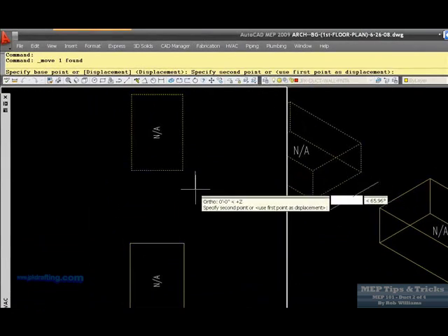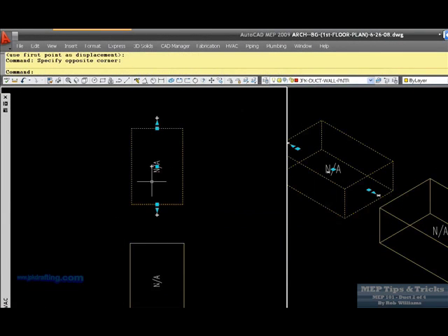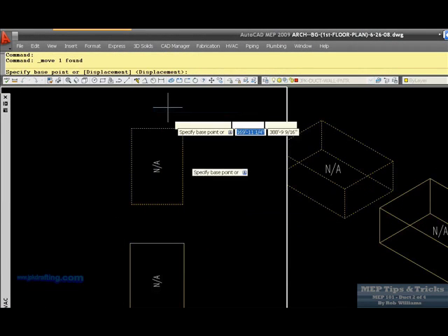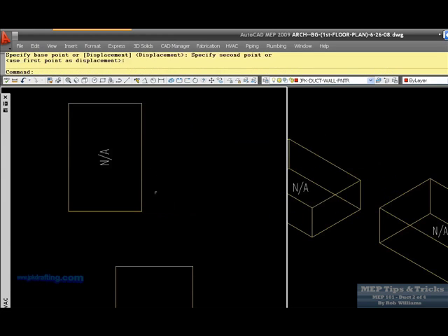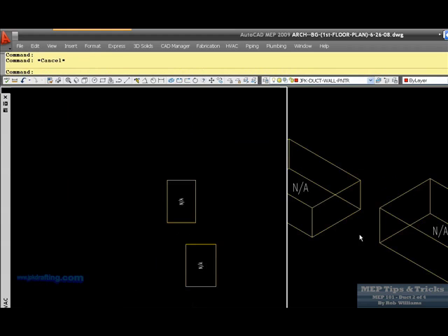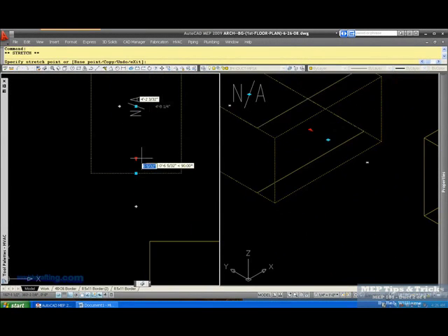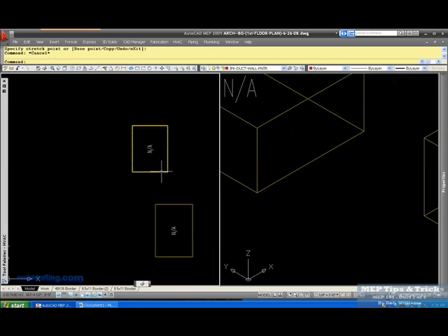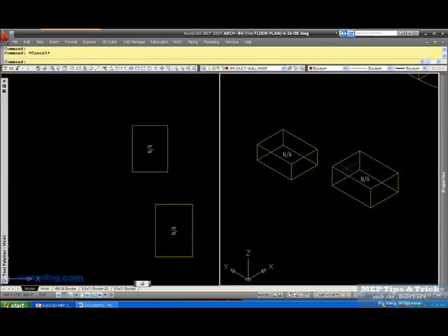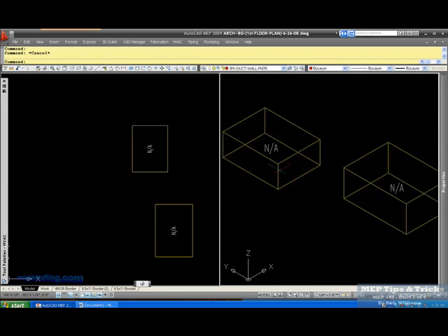Let's say you had a really bastard offset. You just didn't have time to mess with it, and you wanted to go this way, and you wanted to go this way. You wanted to transition it, offset it, all in one. You're probably going to have a heck of a time getting that to work with those fittings. I mean, you can, but you're going to spend 20-30 minutes trying to get it to work. Secret here is the 3D Polyline. Come in.